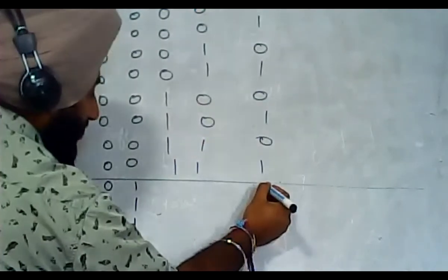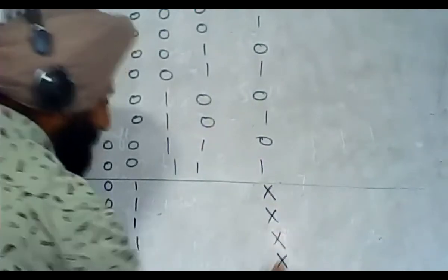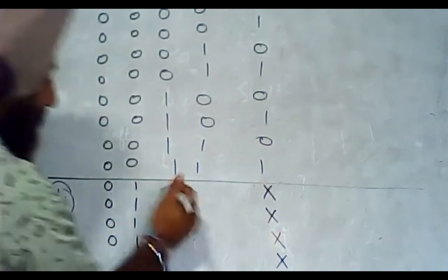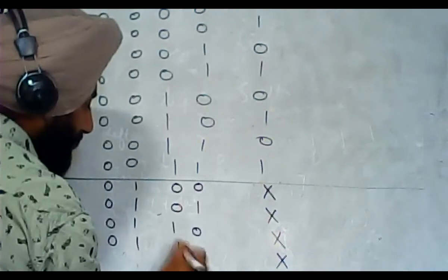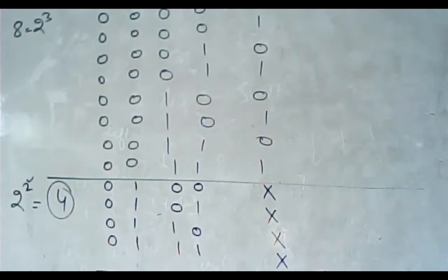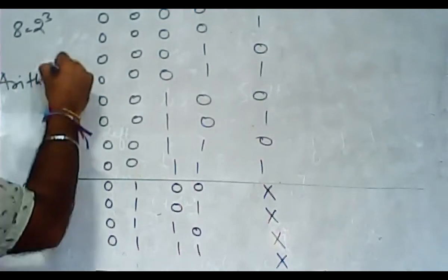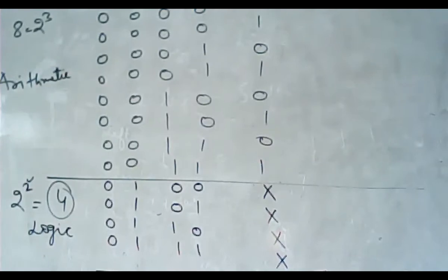And for logic operations, your carry in will be in don't care condition. So for this you have 0 0, 0 1, 1 0, 1 1. So till this point, this is your logic. These 8 operations are arithmetic operations, and these 4 operations are logic operations. I hope the concept is clear.